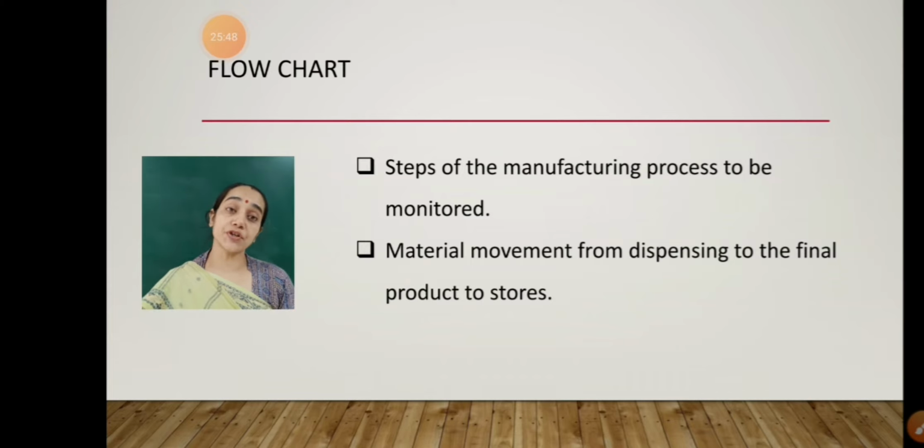Then how it will be shifted to our hopper, and once it has been shifted to the hopper, how much time it takes to flow and fill the die cavity. Then there will be the processing variables of the punching machine: what will be the rate of movement of the die table, and at what pressure the upper punch and lower punch come together to compress the tablet.